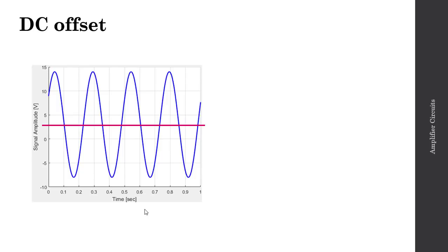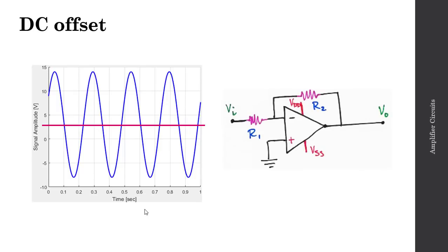And so the problem that I have is that if I connect this signal up to a standard inverting op-amp, often I'll have a saturation occurring, right? Because the maximum output I can achieve is going to be driven by the rail voltages associated with the power supply that I've connected my op-amp to. So if I have a significantly large DC offset associated with my signal, I'll actually get some saturation occurring. I'll actually get some clipping of these larger amplitude AC components.